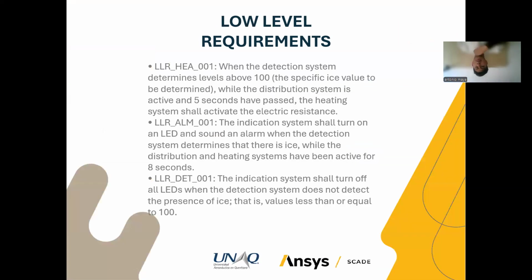What about the low-level requirements? Low-level requirements are those that represent how the implementation is going to be implemented in order to have the system working appropriately. So when we have levels below 100, the system is going to display an LED indicator that is going to show that the icing condition is present at that moment.